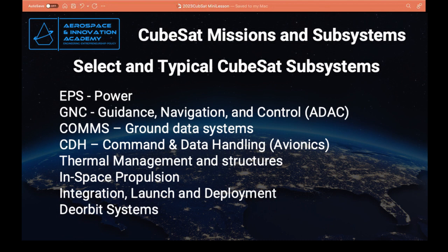So sometimes materials like adhesives and tapes will start emitting gas that otherwise would have stayed in that solid material. That becomes a nuisance for other people, and NASA is very particular about the amount of what they call volatile materials on your spacecraft.